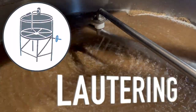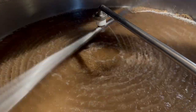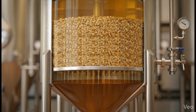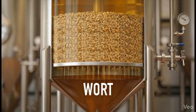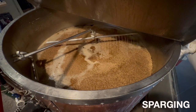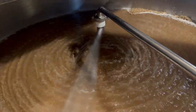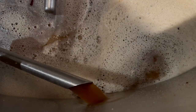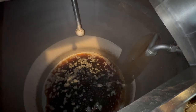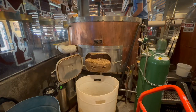Step 4. Lautering. Once mashing is complete, the next step is lautering. The mash tun is fitted with a false bottom that allows liquid to pass through while holding the grain in place. The sweet liquid, called wort, is filtered through the grain bed and collected below. Hot water, called sparge water, is sprayed over the top of the grain to rinse out remaining sugars. The result is a clear, sugar-rich liquid called wort. As the wort leaves the mash tun, it's transferred to the boil kettle. The spent grain is then removed and collected by local ranchers to be used as animal feed.